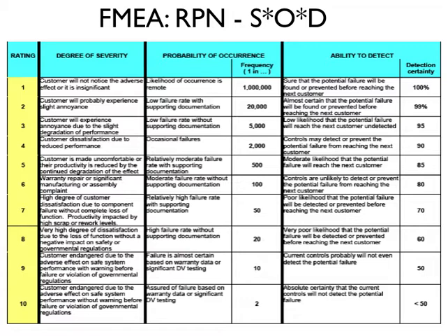And if that information is available, the right side of the probability of occurrence column can be used. And then as a result, it can be more of a quantitative approach to determine the actual rating score. But again, with each failure mode, you'll determine what each value is and multiply those together, and that's the RPN for the particular failure mode.